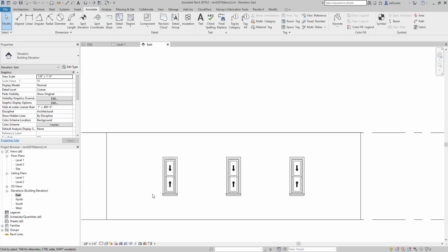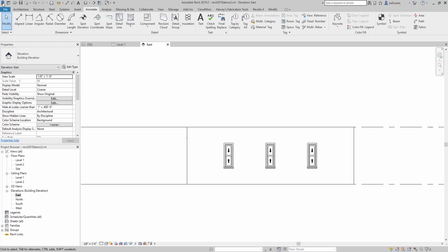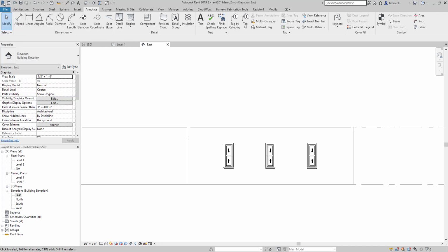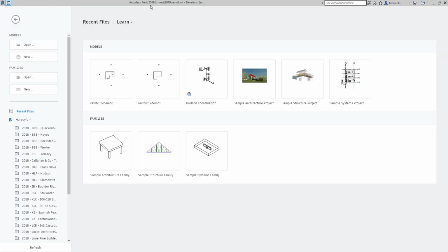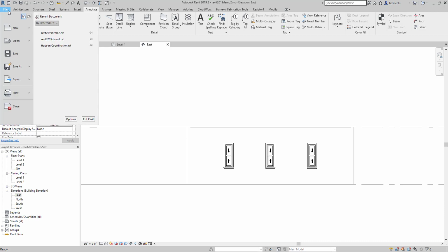One thing I want to show you are the shortcuts. So we're going to go up to the Revit bar up top. We're going to hit File. Yours is going to show a giant Revit button. That's why I was clicking on this one up here. Mine does not show that. That's due to, remember, 2019.2. So I just hit Project Home. You're going to have a giant button up here rather than 3 different buttons. That Revit button is strictly hitting File.